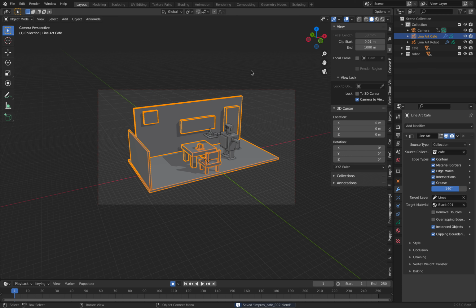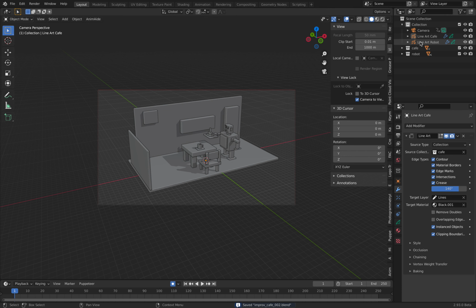When working in 3D, if you keep everything organized, you're going to thank yourself later. So what's happening here? The Grease Pencil is drawn automatically for you from the angle of the camera. You can bake this. Also, you can turn this into something that you can render. I'm going to select all by type mesh, all the mesh, not the Grease Pencil object. I'm going to assign a material. So I'm assigning it to one. Now I want to Command L and link materials to every selected object.